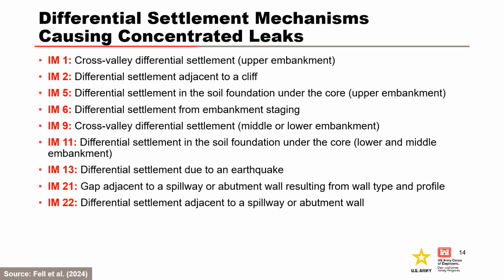There are a wide range of mechanisms that can create cracks or other defects through which concentrated leaks can develop. Many of these are related to differential settlement. The initiating mechanism, or IM numbers, correspond to Fell et al. 2024 methodology used in the RMC Concentrated Leak Erosion Cracking Toolbox, which will be covered after this presentation.